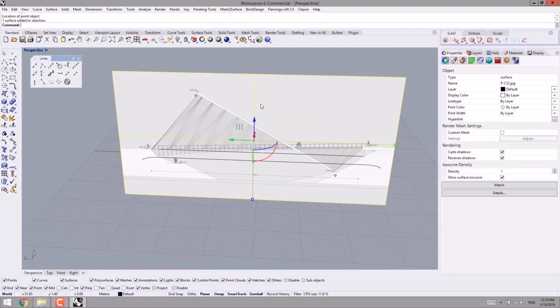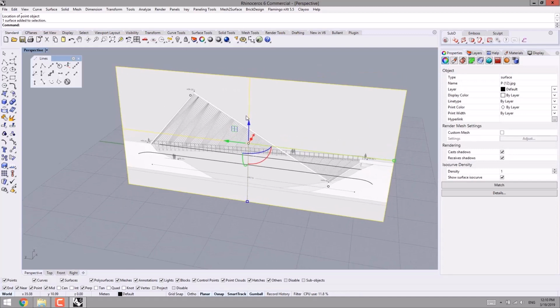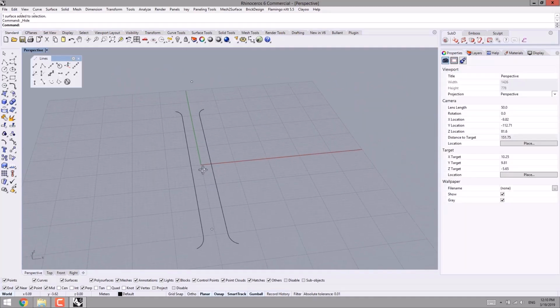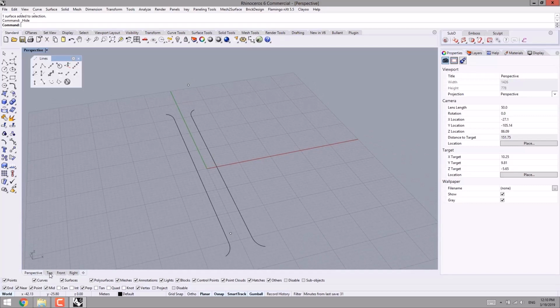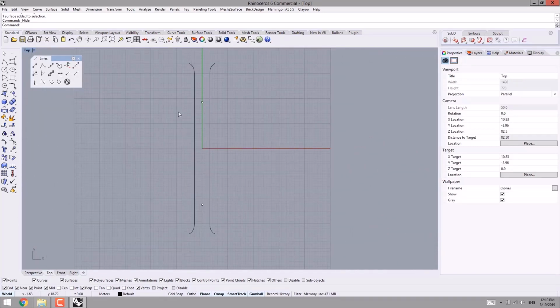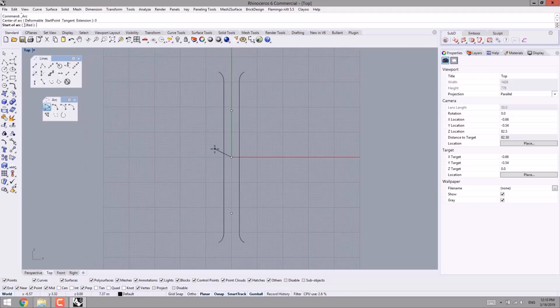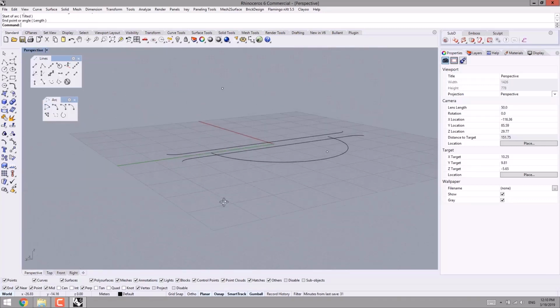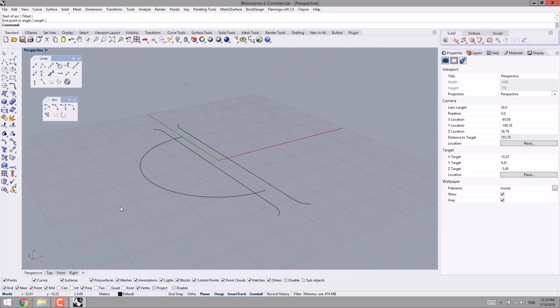As you can see on the screen, I select the image, and after that I hide the image by pressing Ctrl H, and then I'm gonna work on the points. Following that, we're gonna sketch an arc. So in the sidebar, I open the arcs actually. In the set of arcs, I choose arc center start angle, and then from the origin point till another point this way. Let's check it out in the perspective view.